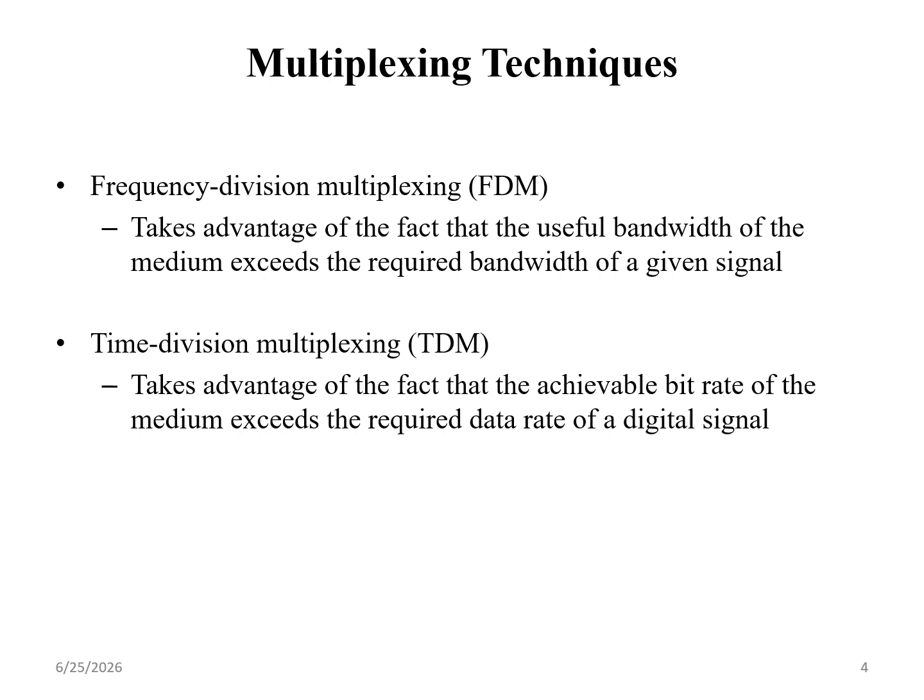As I said, in multiplexing techniques we have various types. The first one is nothing but frequency division multiplexing. Frequency division multiplexing means for each and every user, we give a specific frequency range. They will be communicating to the receiver side with their own frequency. The frequency range will not be changed. That is nothing but frequency division multiplexing.